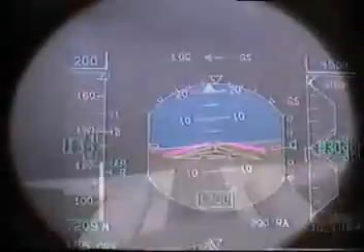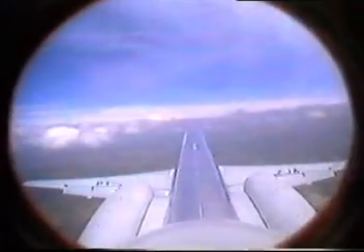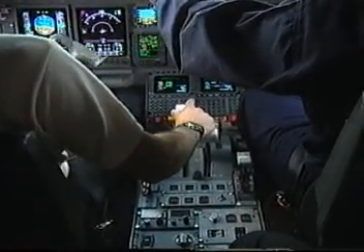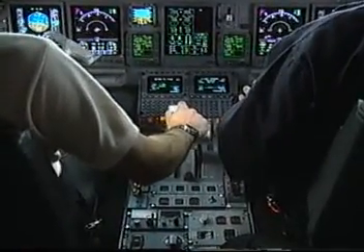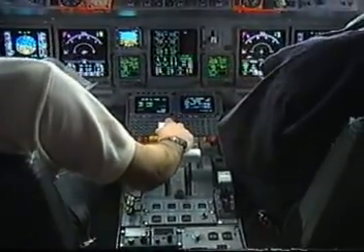Yet, when compared to a straight-wing turboprop, there are differences. Obviously, pilots are supposed to fly at low speed for controllability reasons in a one-engine inoperative condition. But even if control is not a factor, it is very important that the low-speed end of the envelope be avoided to prevent a no acceleration, no climb situation from happening. And if it happens, the pilot must be aware that reducing speed will not increase flight path angle. Let me show you an important characteristic of the flight in high speed.